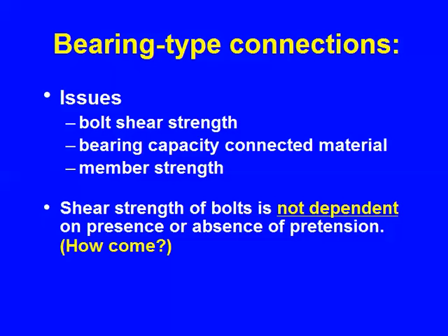Now, this next statement is the first thing I've said to you that's not intuitive. All the rest, you're able to sit back there and say, I knew all that. Well, I hope you did. This one is not intuitive, and if you knew it, that's great. But I'm going to have to work on the basis that you didn't know it. And that is that the shear strength of the bolts, about which I have to talk quite a bit yet, is not dependent on whether I pre-tensioned the bolts or didn't pre-tension the bolts.